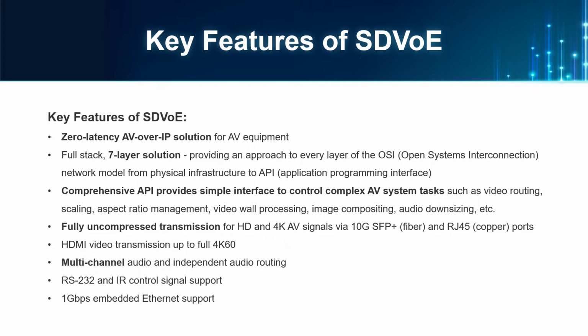And IEI also provides comprehensive API with simple interface to control complex AV system tasks. About signal transmission, it provides full uncompressed transmission for HD and 4K AV signals via 10G Ethernet ports. It also supports multi-channel audio and independent audio routing, and I/O control signal and 8G Ethernet support.